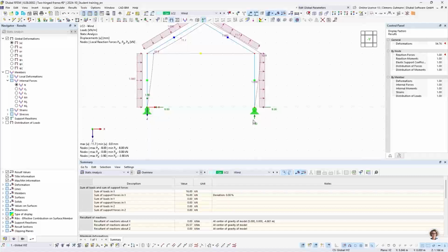And that leads to a force pair, a compression support reaction on the right and a lifting support reaction on the left. So yeah, this is interesting because you might need to design the connection for the left side accordingly.